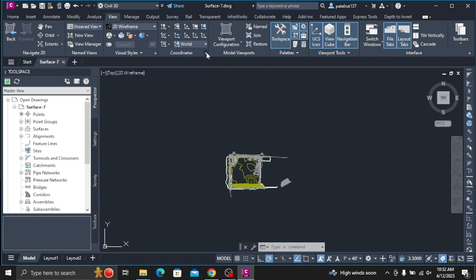Click Modify tab, Ground Data panel, Surface. Click Surface tab, Surface Tools panel, Move to Surface drop-down, Move blocks to surface. In the Move Blocks to Surface dialog box, in the Select Block Reference Names field, select Light Pole 01 and R4-7A Keep Right. Click OK. Each selected block moves from its current elevation to the surface elevation at the block's insertion point.